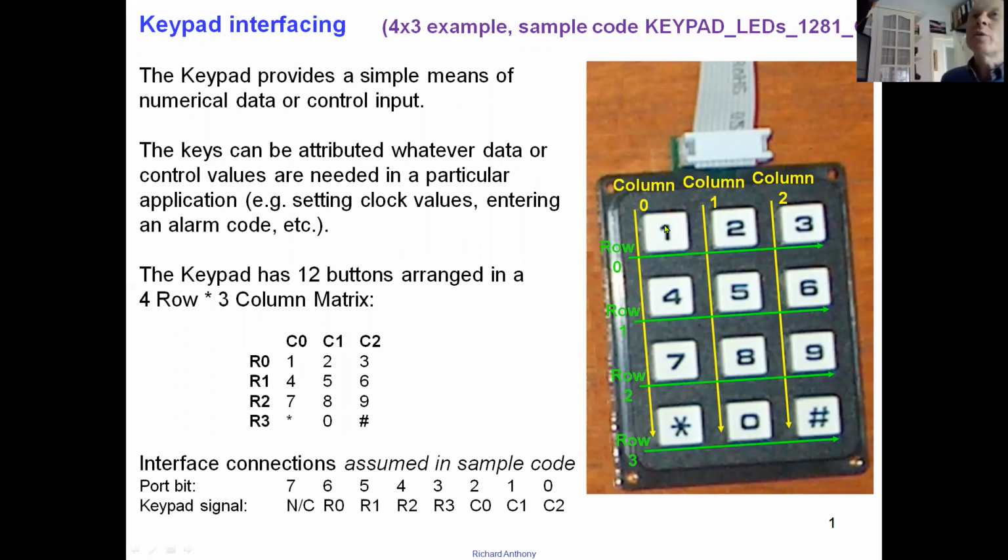And then all these switches, right? So how are we going to do this with less? How can we, for example, take a 12 key keypad and connect it with only 7 wires? Well, you can do it like this. If you have a single wire that runs along all of these switches on one side of the switch, and another one that runs along there and there and there, you only have 7 wires. And when this switch is pushed, it connects these two together and all the others are left unconnected, right?